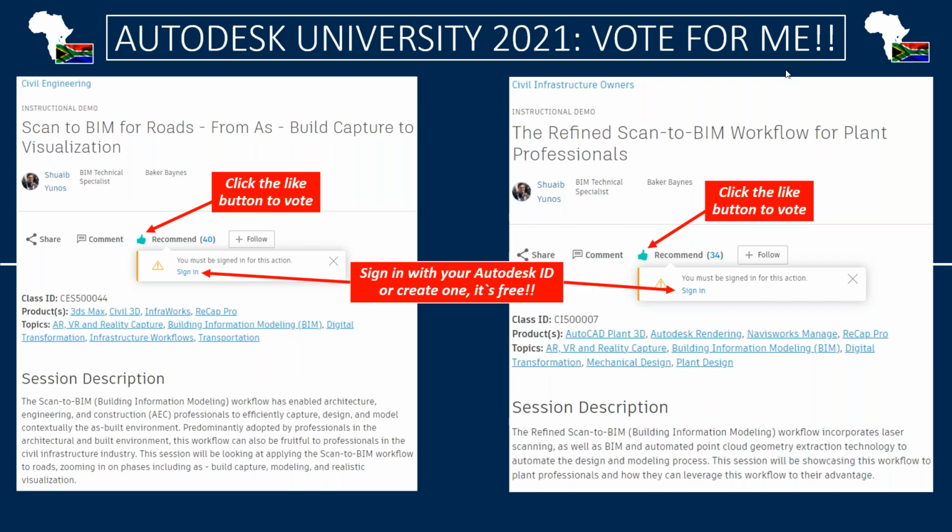It is developed in this manner where you would need to use Inventor. And I definitely see the value for it. Yes, if you are involved with a lot of bridges, it is definitely wise to at least get one Inventor license so that you could actually model the bridges in a much more streamlined manner, because it allows you to create custom parametric parts and bring them directly into Infraworks, which then can be linked to the detailed final bridge structure in Revit. Should there be any updates, it will synchronize, or it will prompt you to synchronize it.